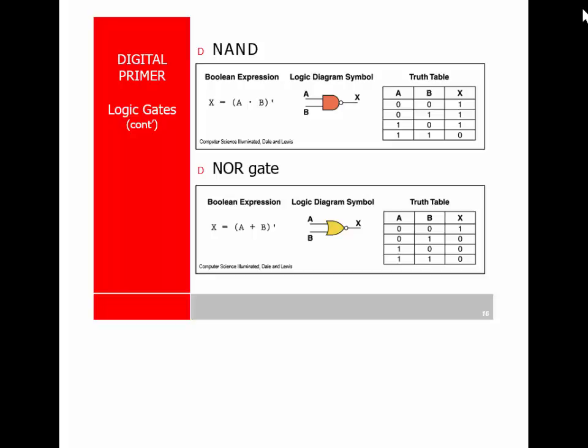What it is, is a chip that has digital logic on it in the form of a gate array, along with a microprocessor core built into it, or multiple microprocessors, right there. So you've got the system on a chip. Actually, when we look at our 8051 microcontroller that we're using, it's a system on a chip essentially, because it's an 8051 core with lots of stuff put around it. That's there, and it's done as a gate array, right there.